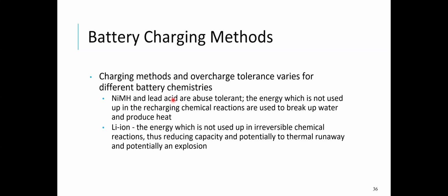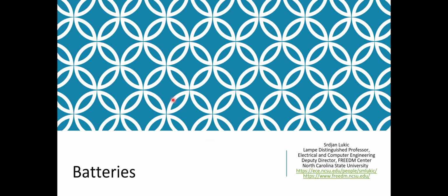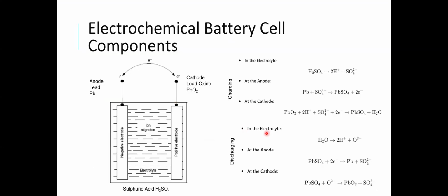when I'm overcharging the battery, and actually it would be fun to go back and look at that. When I'm overcharging batteries, so charging, I will produce, like I said, in the electrolyte, hydrogen. So this H2 plus can actually recombine and become H2O if it combines with some electrons. So this will become H2O, hydrogen. And so as I'm overcharging the battery, I'm basically producing hydrogen.